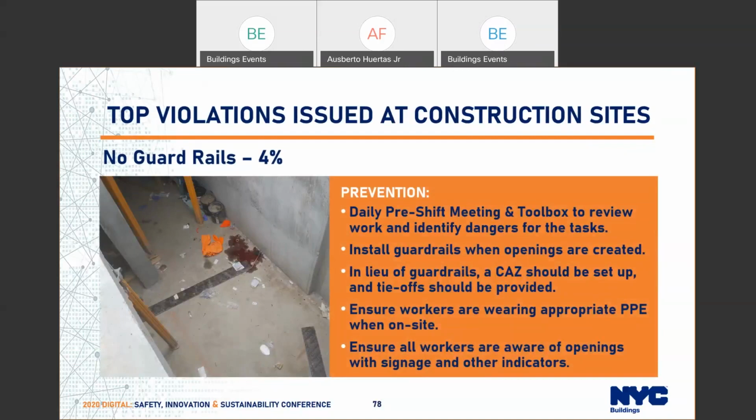Preventative measures to be considered are daily pre-shift meeting and toolbox talk, install guardrails when openings are created, and do not move guardrails when in place unless absolutely necessary. In lieu of guardrails, a controlled access zone should be set up and tie-offs should be provided. Ensure workers are wearing appropriate PPE when on site. Ensure all workers are aware of openings with signage and other indicators.